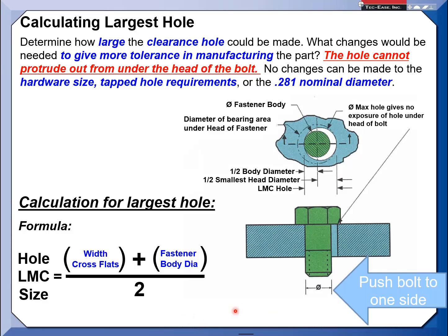I had the opportunity, being at the ASME meeting, we actually had a major automotive manufacturer come and present to the 14.5 committee talking about this very subject. And they use this practice. When they looked at a vehicle, they made the assessment that 85% of the holes in the vehicle, all the fastener was doing was a clamping force, not a key locator.